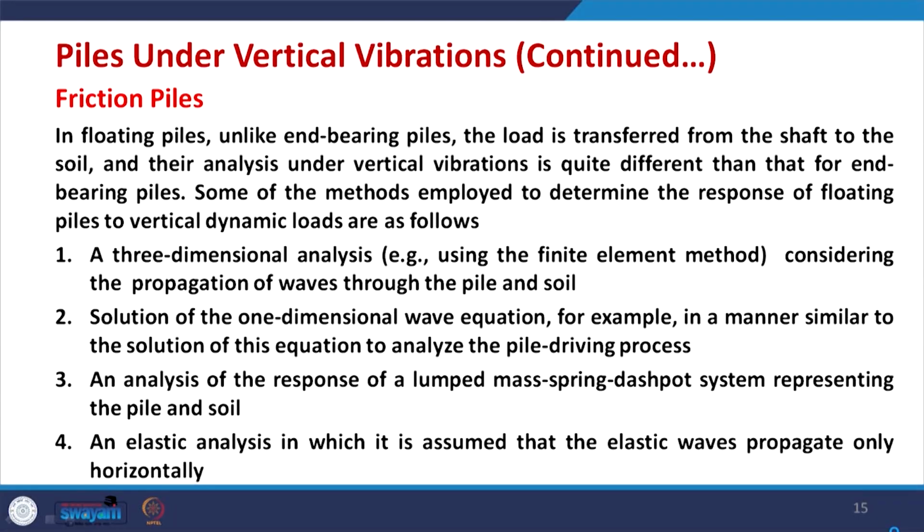These are similar to what we have discussed. First, 3-dimensional analysis, which can be done only using the finite element method, considering the propagation of waves through the pile and soil. Then the solution of the one-dimensional wave equation, for example, in a manner similar to the solution of this equation to analyze the pile driving process. Third, an analysis of the response of a lumped mass spring dashpot system representing the pile and soil. And fourth, an elastic analysis in which it is assumed that the elastic waves propagate only horizontally. So, these are the assumptions for friction piles under vertical vibrations.